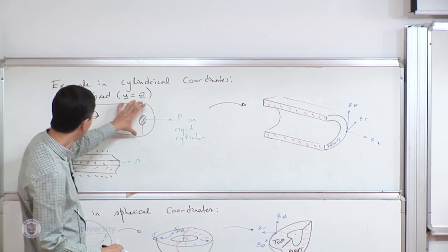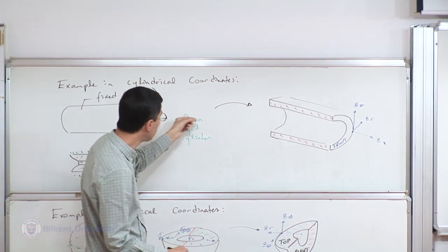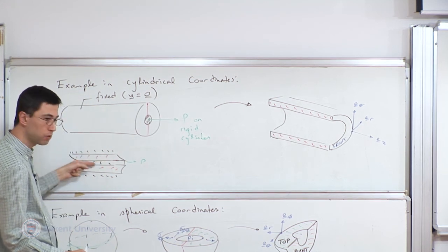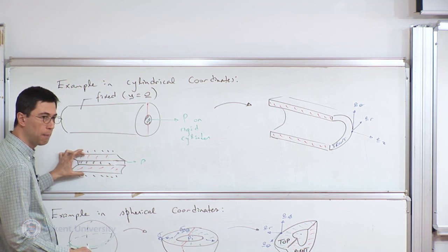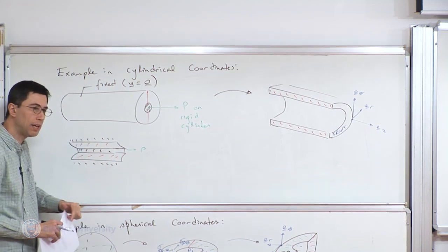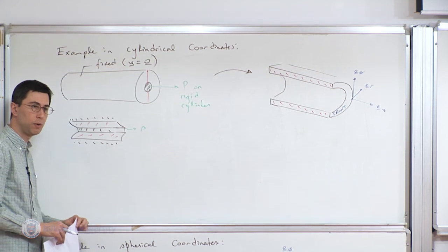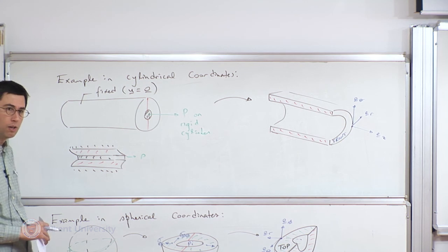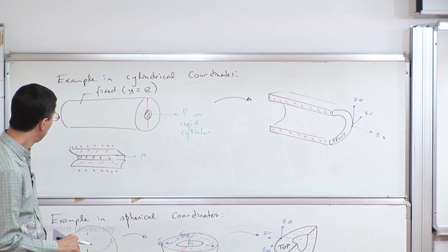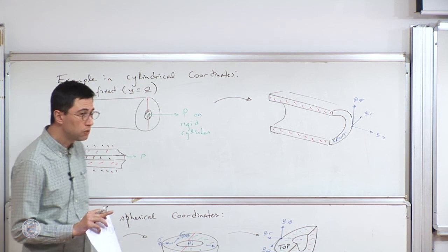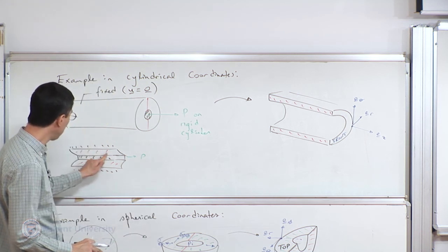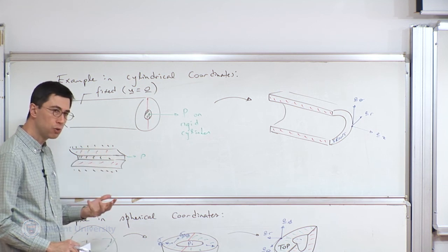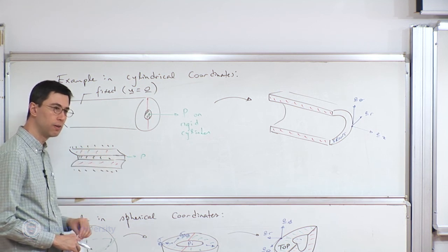Well, the outer surface is fixed, yes. So I'm pulling on the inside, right? So the inside will try to move when I take this cut. So there is for sure some displacement. The outer is zero. But I'm talking about the components U_r, U_theta, U_phi. One of these is for sure zero from the outset. Ah, that's good. It's not very easy to see. The displacement in the radial direction, it's in that direction. So he's saying it's zero. Actually, it is true. It's zero. Okay? But what else is zero?